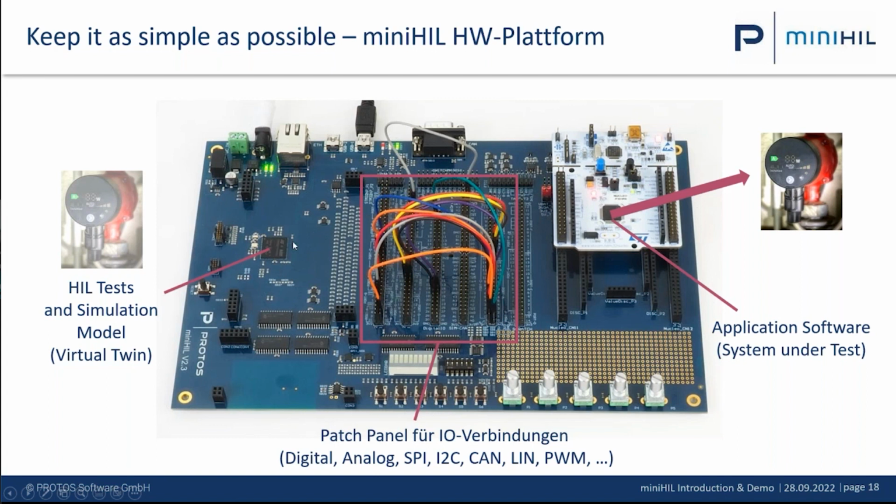And here on this side, we need the environment simulation, so the plant simulation for the motor, for the battery, for the CAN bus communication, and so on. And so we need the simulation, and we run the test cases also directly on this microcontroller here. Typical signals we have is digital, analog, SPI, I2C, PWM, and so on. So the typical low-level interfaces. So now let's have a look at this part here.